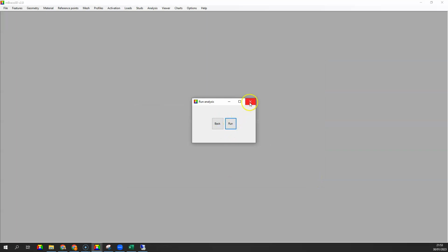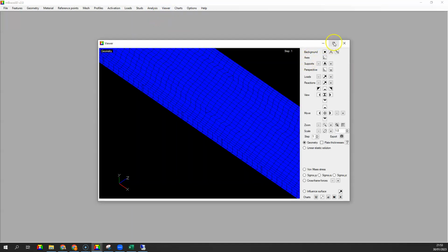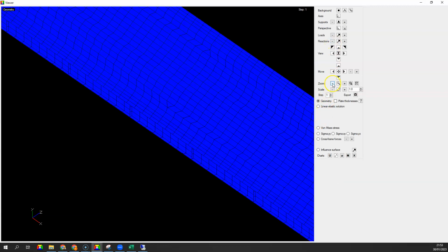We can run the model, but really this will take about 7 to 8 minutes because we're applying a unit point load everywhere on the deck, and then building the influence surface. We have to do that many times because there's many nodes, and then the solver, another subroutine, will find the critical vehicle load positions. So instead, let's just go to the results.